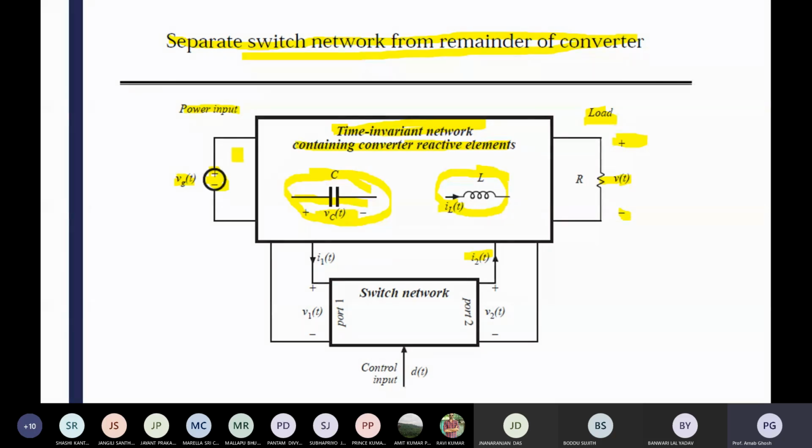In the case of an MPPT, a maximum power point tracking converter, you are also using some switching converters. What is the purpose of the switching converter? It provides the voltage; the output of that converter is always a voltage, and that voltage is fed to the DC bus. The DC bus, or DC link voltage source, will always take the power from your renewable source, the solar panel. It extracts power from the solar panel and gives it to the DC link voltage, the bus voltage.